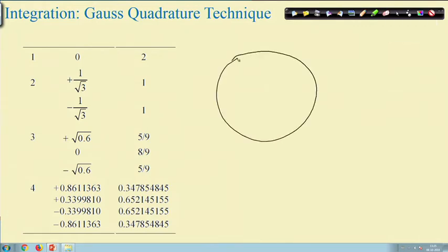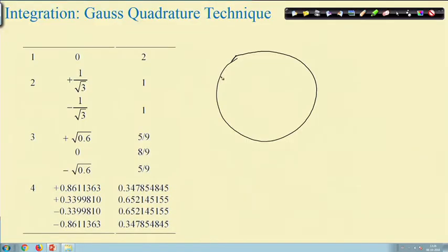Now, if we want to discretize this circular domain with a triangular element or quadrilateral element, your discrete domain may not be an exact representation of the actual domain. In a limited sense, yes, if you keep on increasing the number of elements and reducing the size of the elements, all this curved boundary can be closely approximated.